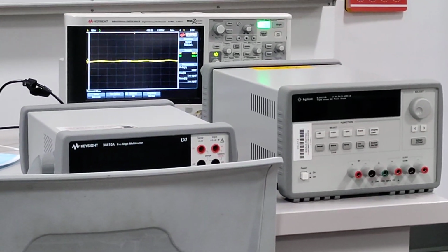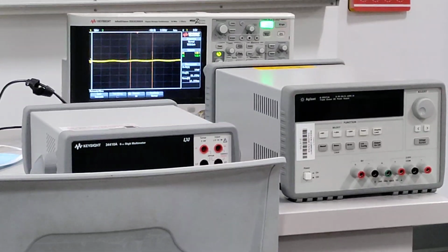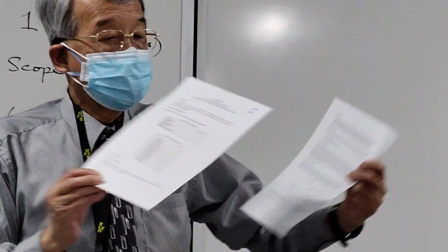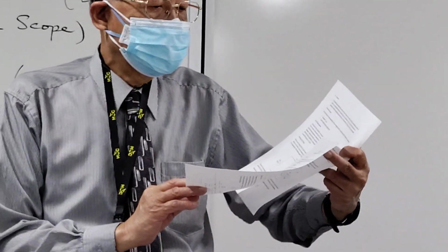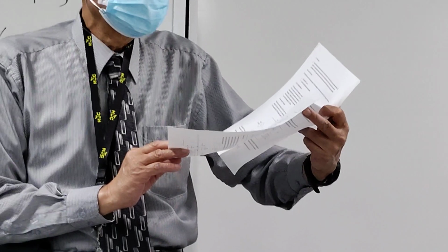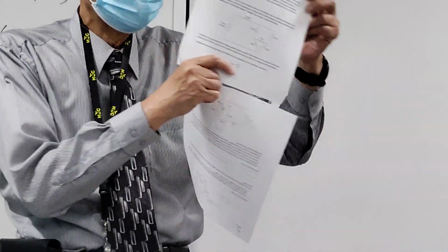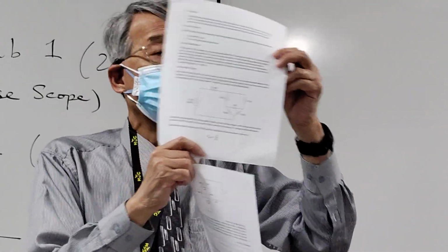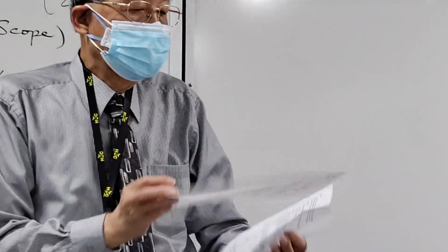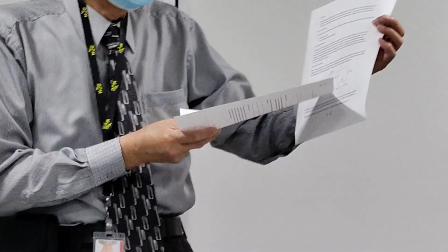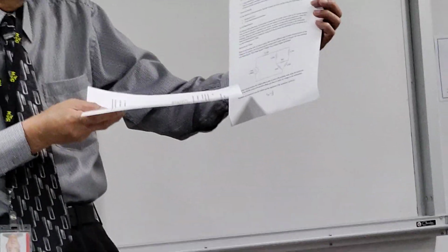While we're waiting for Stephen, I just want to show you the documentation. Each one of you already has the documentation anyway when you print it out, right? So Lab number 2 is about the linear circuit, to build a very simple resistor circuit, like this. So like a bridge circuit, okay? So basically they would like to have you measure the voltage and current across the circuit in here.